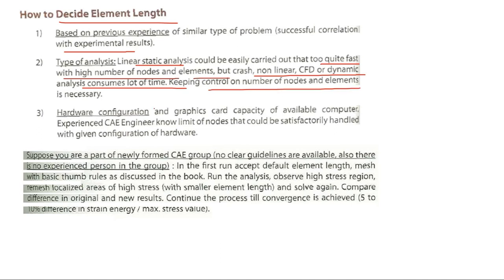Keeping control of the number of nodes and elements is necessary. We keep only the necessary elements, no need to increase the number of nodes. Hardware configuration and graphic card capability also matter; an experienced engineer knows the limits of nodes that can be satisfactorily handled with the given hardware configuration.